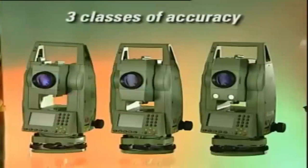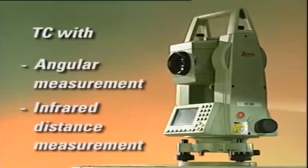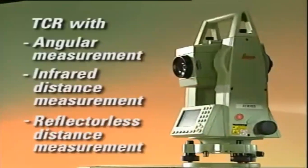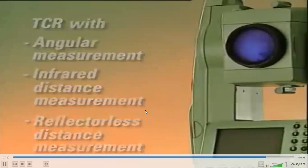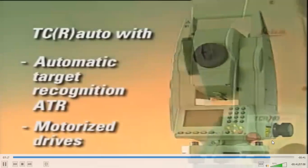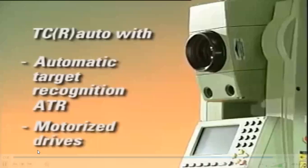The TPS 700 is available in 3 classes of accuracy and in various levels of equipment. The base model, TC, with tried and tested Leica angular and infrared distance measurement. The TCR model, in addition, features reflectorless distance measurement. The top model, TCR Auto, offers, in addition to classic manual operations, all mentioned advantages like automatic target recognition or motorized surveying.